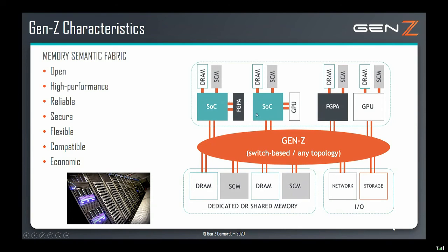But those processors obviously need to have coherency sorted out very strongly. Gen-Z does not automatically do coherency or manage coherency. It really allows access, and then a coherency layer would be separate communications between these processors. But essentially, the capability is there, and the hooks are there to make it work. And there is a peer-to-peer coherent op class, which would be used for coherent transactions if the memory is truly shared. So yes, that can be supported with Gen-Z.